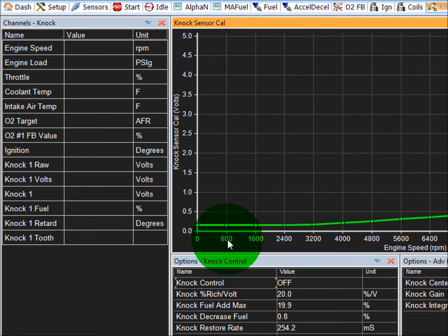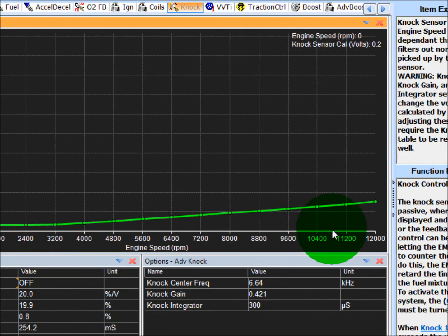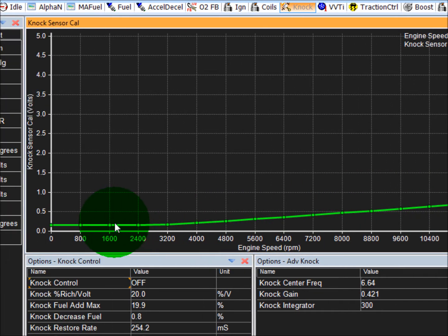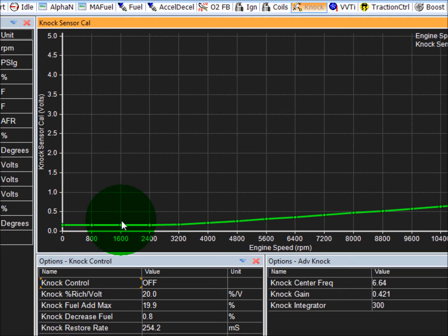The values that you get at all of these RPMs will be plugged in here. However, put this line right above all of those peaks. Anything above this line will be considered detonation, and anything below this line will be considered knock free.